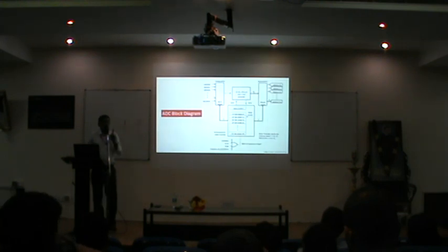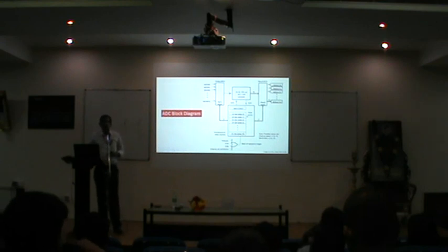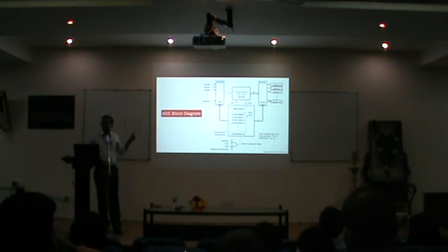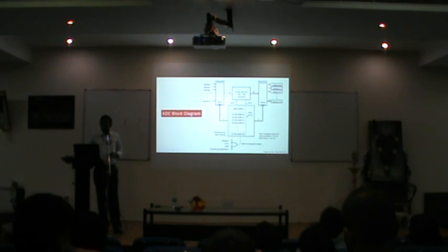Now it is not just one single quantity which usually you will be sensing. Take the case of a 3-phase inverter. You have the requirement to sense at least 2 of the phase currents and 2 of the phase voltages. If you go for unbalanced conditions, 3 currents, 3 voltages. So obviously you have a requirement of more than 1 ADC channel. So usually manufacturers will provide a setup where you have different channels available.